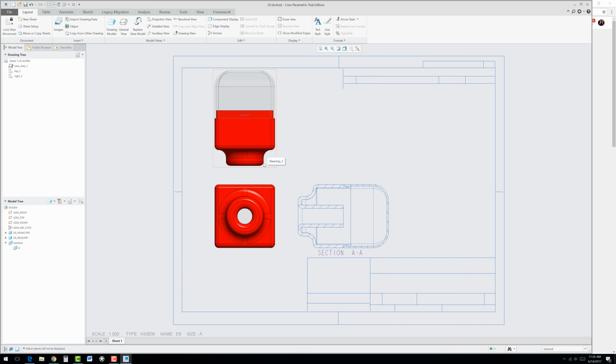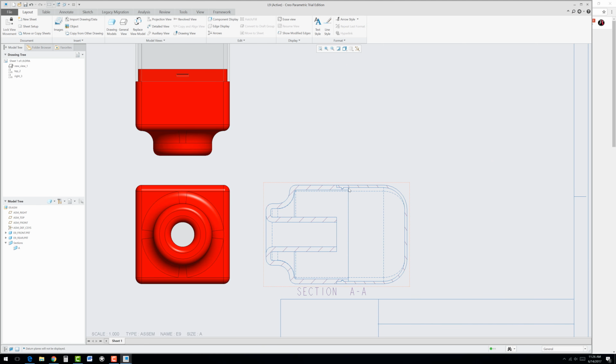Why not? Okay. Now we're going to make a detail view of this region right here. To make a detail view, go to Detail View, and click right in that little area there. You get the little X. Start at 12 o'clock above it. Imagine there's a circle around here. Go to 9 o'clock, 6 o'clock, 3 o'clock. Remember, you don't have to completely close it. Once you get to 3 o'clock, middle click, and now left click up here to drop the detail view, which should automatically bring you into a view that's twice the size. And then just straighten these notes out a little bit, perhaps.